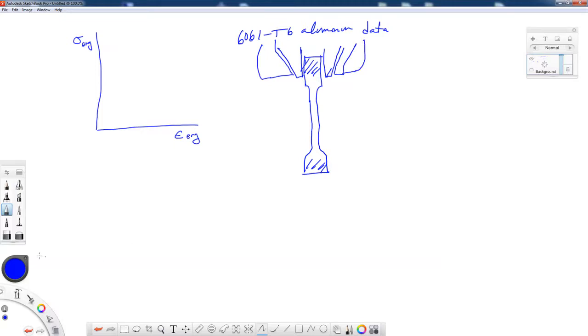Something like that. And as these grips are tightened, as the specimen is pulled, these wedges in tension tighten up in this matching slope right here. And this is the same thing down on the bottom. But in order for you to start the test, in order to initially get it started, you have to apply a little bit of preload. So there may be 100 to 200 pounds preload, depending on how much force it takes to bite into that specimen.